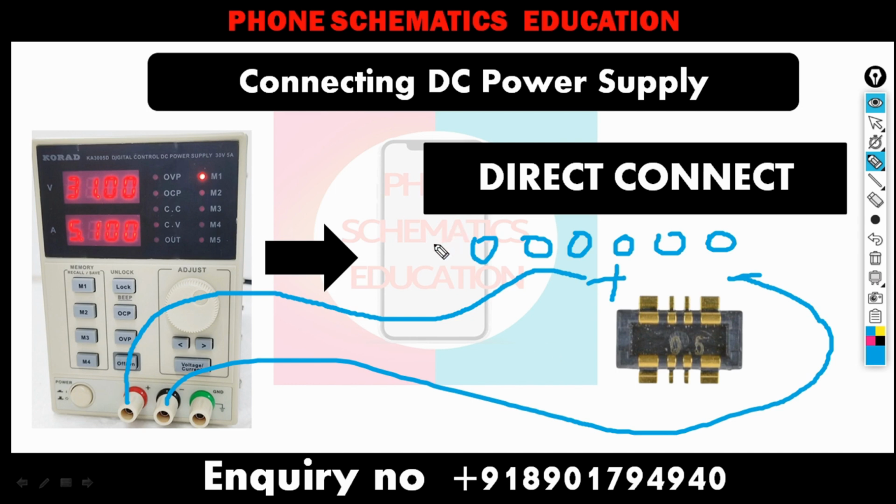So you can find which point is VBAT, right? For this, put the multimeter on beep mode, one probe on the positive, and check one by one. Whichever pin beeps, like this one, this is VBAT.